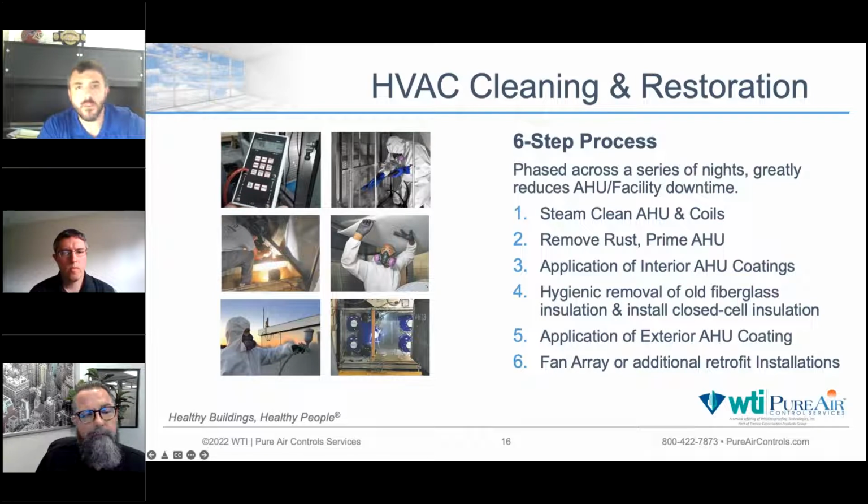And of course, you want to do all the things to get the air handler prepped. Remove as much rust as you can. Do any patch and seal and repair necessary. That part of it is also dictated a lot by location. That can get labor intensive, but if you have a location where it's worth putting the time in to put a new floor in the air handler, then so be it. So all that can play a part in it.